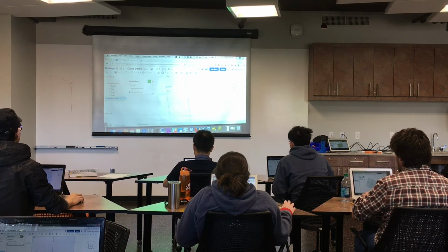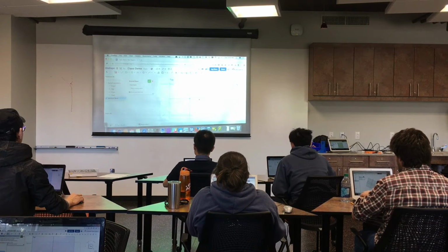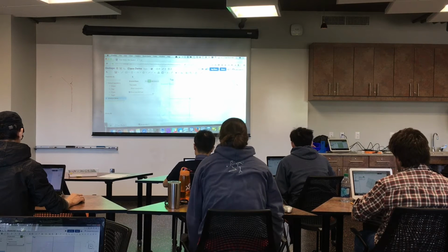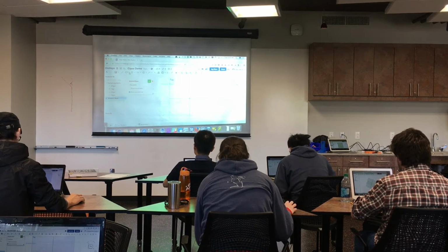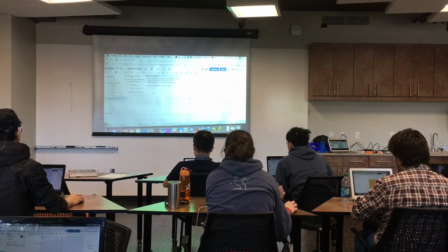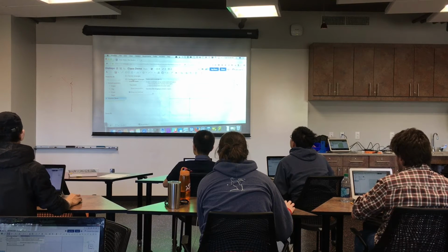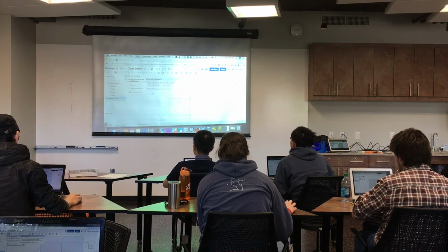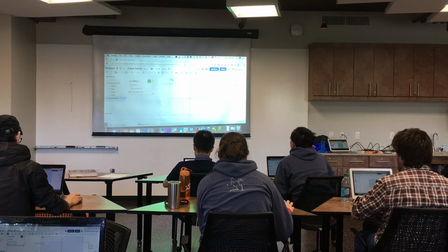And then up here is all the different geometries that we can draw. So I'm going to go ahead and press N, so I'm looking straight down on my sketch. And I need a rectangle for that part. So here's a rectangle. And if you click this little down arrow, you see that there are two types. There's a corner rectangle where you define the two corners opposite each other, and there's a center point rectangle. Well, it's most useful for me to do the center point rectangle because I want this entire part to be centered on the origin of my coordinate system here. So go ahead and click center point rectangle.